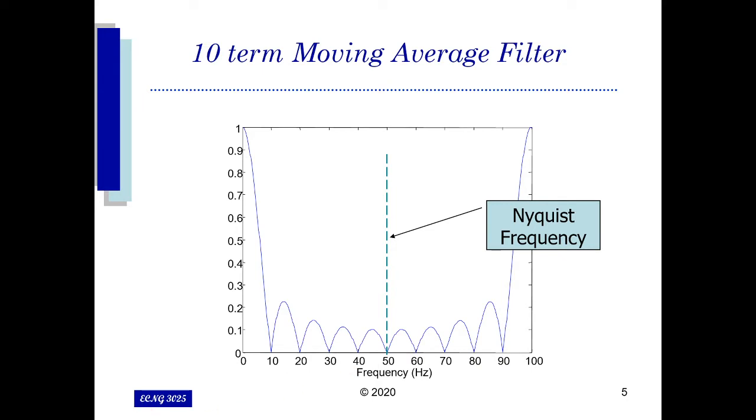So that actually is the end of the design of a moving average filter. We just need to calculate for what is N and where the zero crossings are, and then we just use the generic equation of 1 divided by N multiplied by x[n], x[n-1], and so forth, all the way up to x[n-N]. And that is basically our difference equation that is required for any moving average filter.